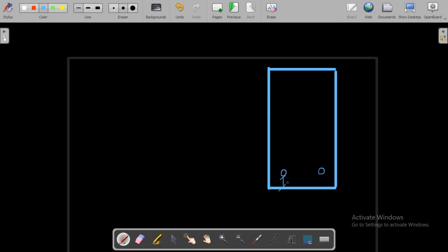This is the clear cover and the spacing in between the bars. This one will be the spacing, this one will be the bottom cover and this one will be the side cover. I will discuss these covers, what the ACI code criteria is for the side cover and the bottom cover, in an upcoming lecture, but these are the steps which I have already explained, and we will cover these checks in the design process when we design a beam.